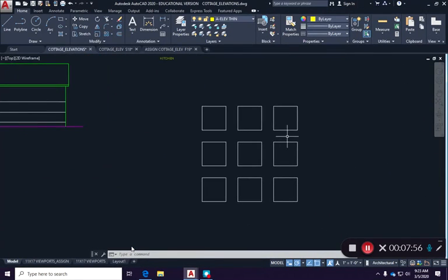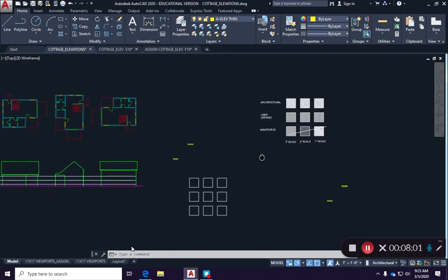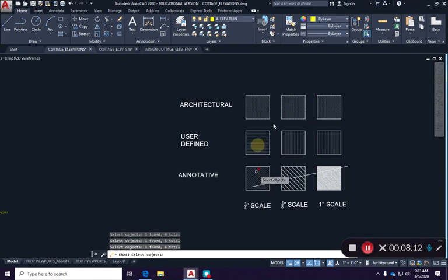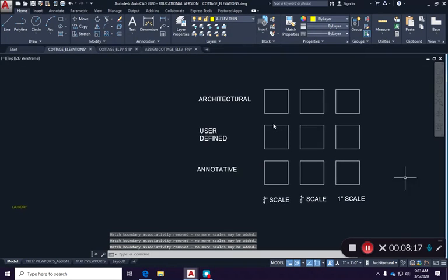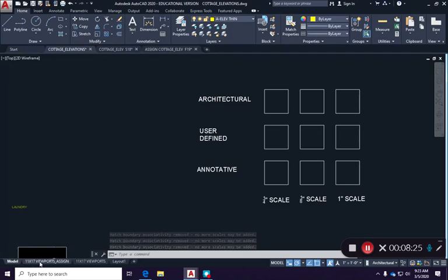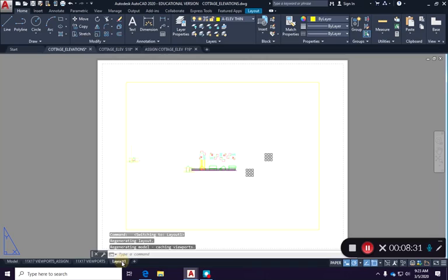So hopefully you have these all 8-foot by 8-foot squares. You can keep your squares. I'm going to move over here because I've got some notes I want to show you. Let's make sure that you all have some viewports on another sheet of paper, on a layout, because that's what makes this really interesting. So if you go to the bottom, you're in model space right now, click on layout one. You have a sort of naked layout with nothing in it.